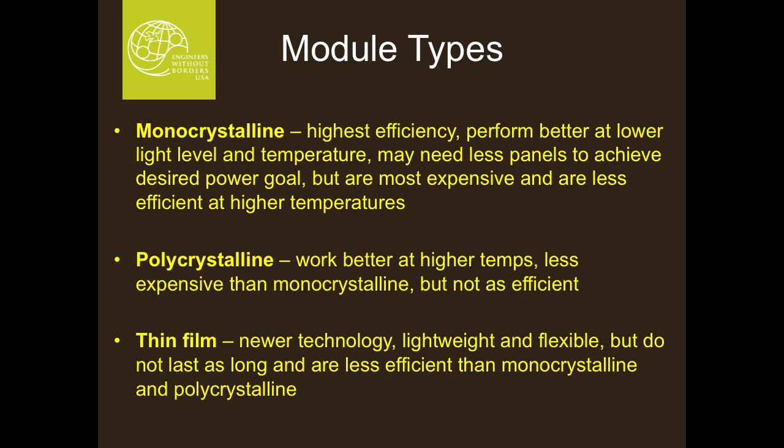There are several different technologies used to build solar modules. These include monocrystalline, which have the highest efficiency, polycrystalline, which have a slightly lower efficiency, and thin film technologies, which are significantly less efficient than crystalline technologies. Of course, efficiency isn't everything. What's really most important is the cost of energy for the module over time. One commonly used measure for purchase is dollars per watt, or cost per watt, though this does not tell the whole story of cost reduction over time.